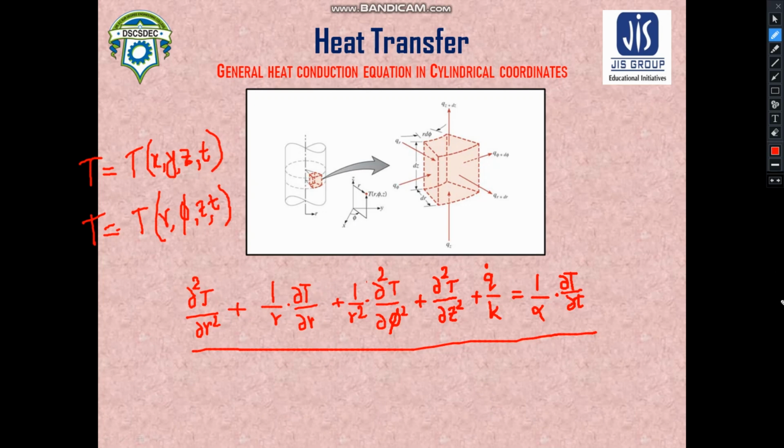So you must remember this equation, since while describing heat transfer in cylindrical objects we would require the application of this formula. But generally, as we are much more worried about only 1D heat conduction, that means one-dimensional heat conduction problems, we would require the heat transfer in the radial direction.